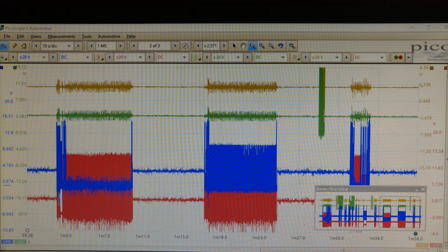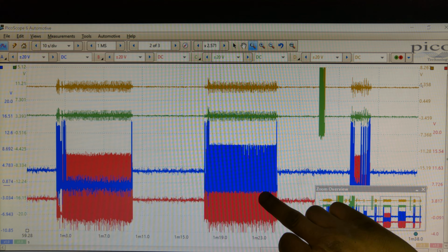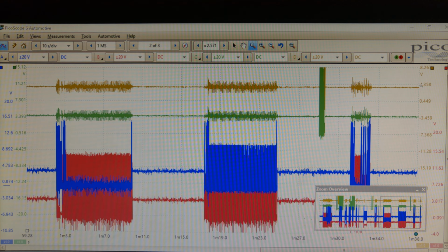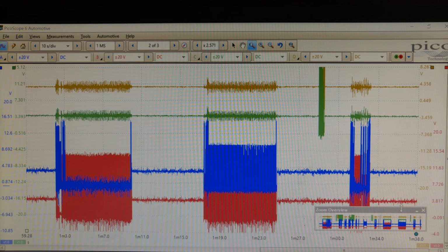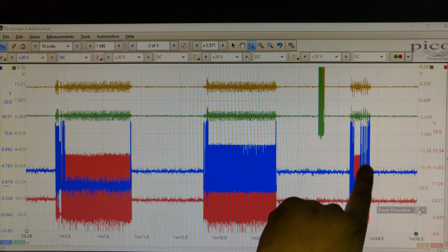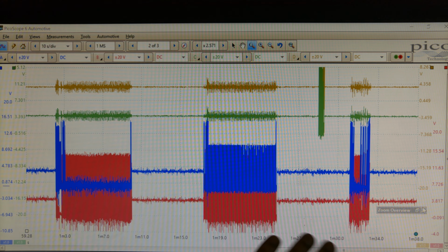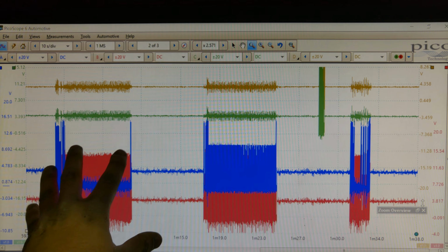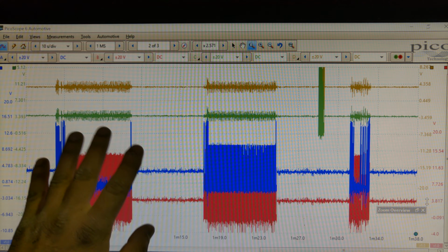I was revving, the car is on the hoist, the wheels are free spinning, so it might be just changing gears when I was revving. So you get activity there and here as well. And this one too, you can see the activity. I'll just minimize that, and this one starts working, the bottom actuator. So both actuators start working on drive, but on reverse I can only see this one. The bottom actuator is the only one doing something.